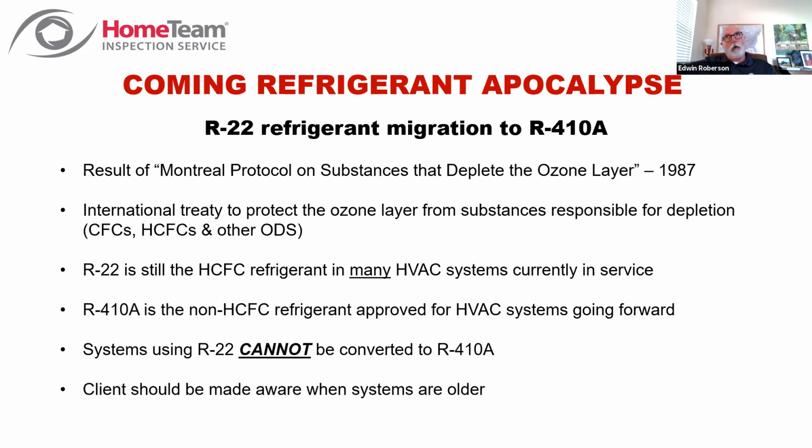I think by 2010, all of the newer systems were coming with R410A. It started actually before that, but by 2010 they weren't installing any more systems with R22. So the majority of your systems with R22 probably are cycling out now.